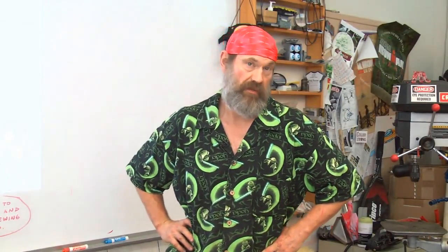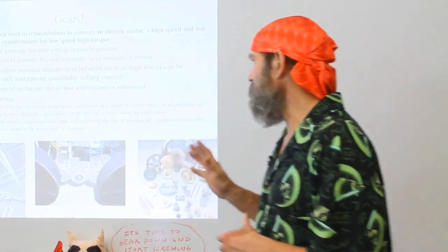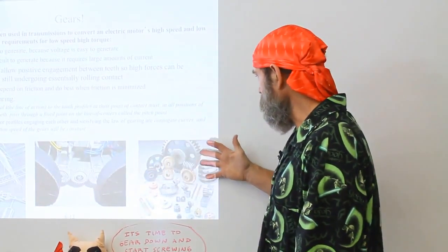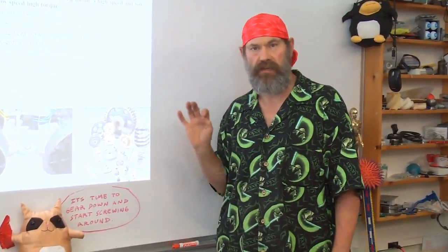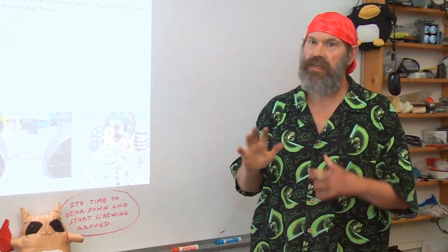Now we're going to talk about gears. Gears are essentially like a screw. It's a type of transmission. And always, like any machine element, Newton's laws prevail. Friction, parasitic air motions, all these factors that affect any other kind of machine element affect gears. Gears have the added interestingness that the actual shape of the contact profile of the teeth can have a huge effect on life, sound, and dynamics.